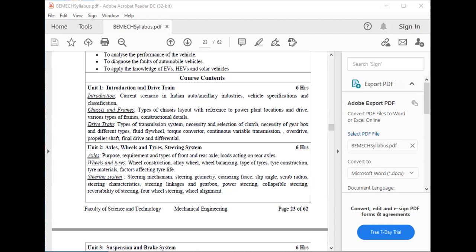Okay, so whenever we apply the clutch, at that time we separate the engagement of transmission system and engine. Okay, when we apply the clutch pedal, then engine is in working condition, but the gearbox gets disengaged from the engine. So the speed in gears becomes stop, but engine is continuously running. Okay, so this is the function of that clutch.